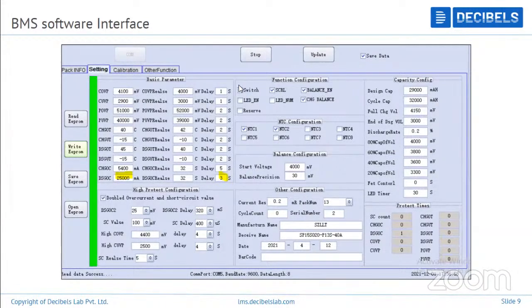After the delay time is over, it rechecks. While rechecking, it will make sure that the release values are reached. If reached, then it will reactivate the complete module. If not, it will again deactivate and cut off. Right, this is how usually a BMS works.